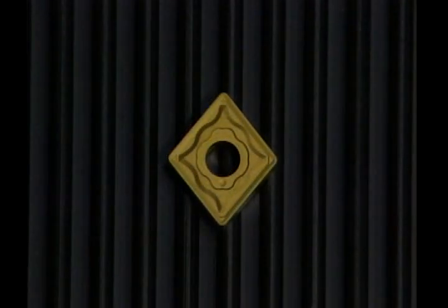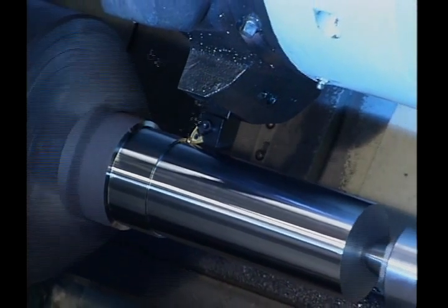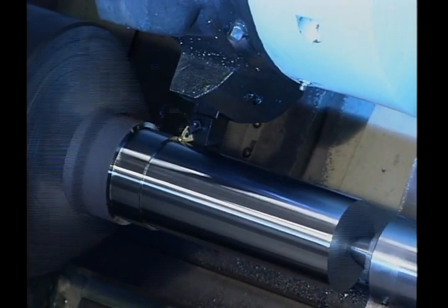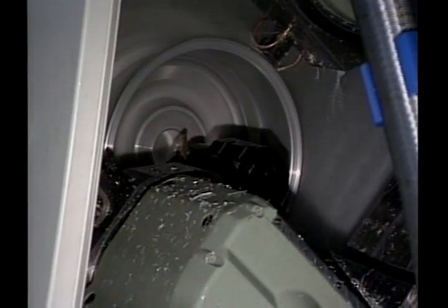Grooves, bumps, waves, dimples, and all sorts of shapes have been designed into cutting tools. Chip breaker geometries are all designed to work at designated feed rates and depth of cut. High-pressure coolant effectively promotes chip breaking if all else fails.